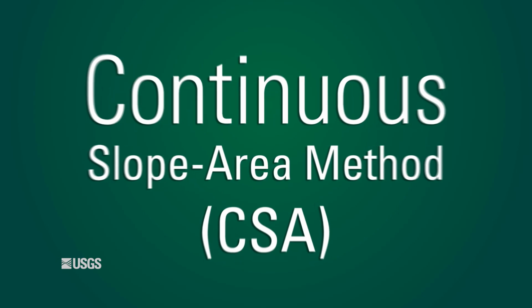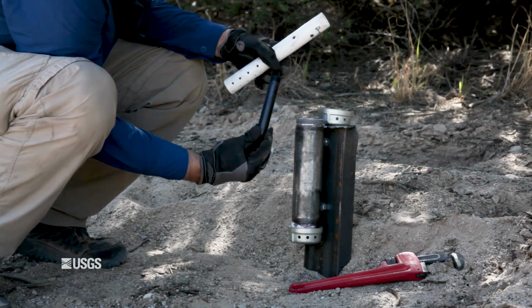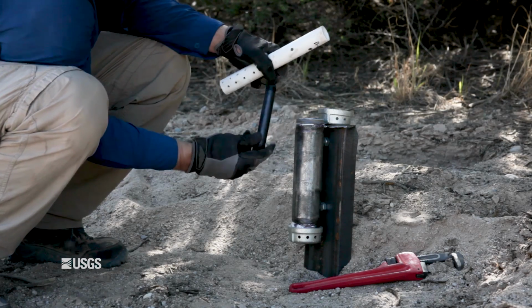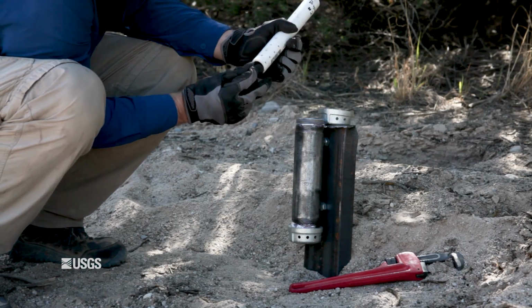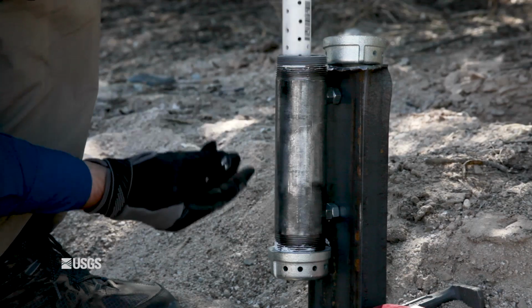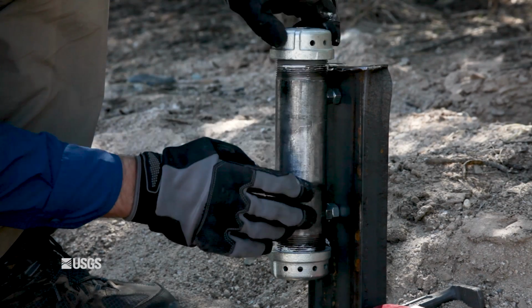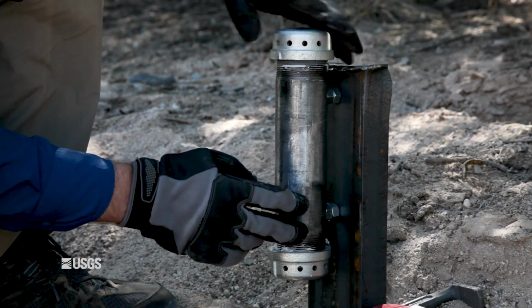The USGS has been working to develop a new method to measure stream flow throughout the entire event, providing more robust data during the rise and fall of floodwaters. This new method is the continuous slope area method. Its procedure is quite similar to the traditional slope area method and builds upon this foundation by utilizing 3 or more continuously recording pressure transducers within a stream reach. These sensors are quite small and can be installed at existing stream gauge locations. When these sensors are properly installed, they can more accurately document water surface profiles than surveys of high water marks.